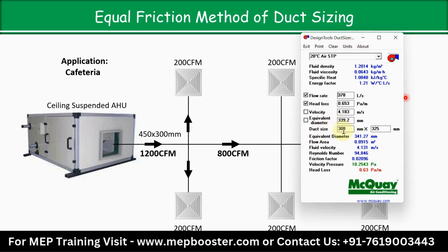So now again, as I told you, for the straight duct or the main duct, always try to maintain the height constant at 300 only. As per this 300, we have got a width of 325. But here remember, we don't need to select 325. We have to select the width 350.